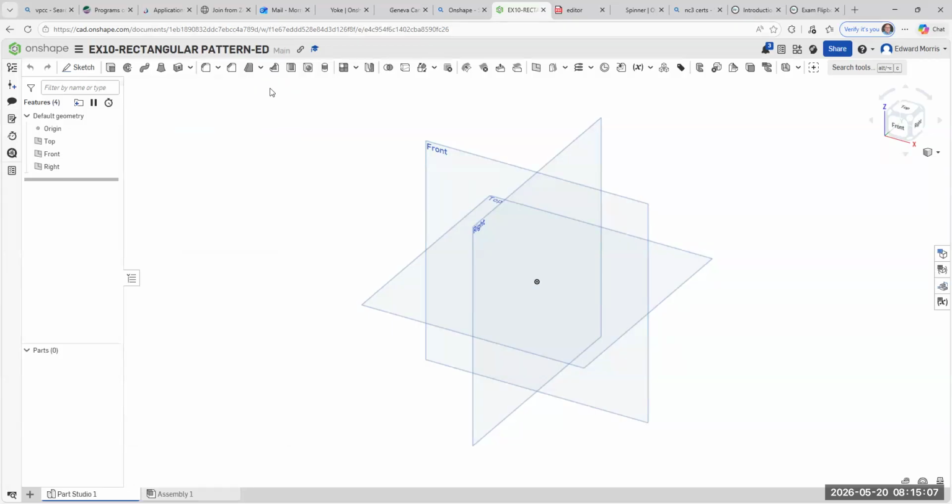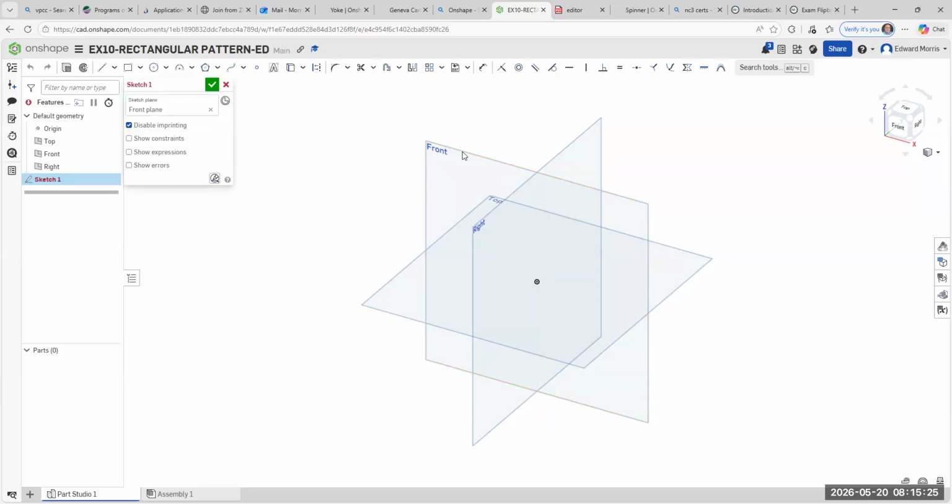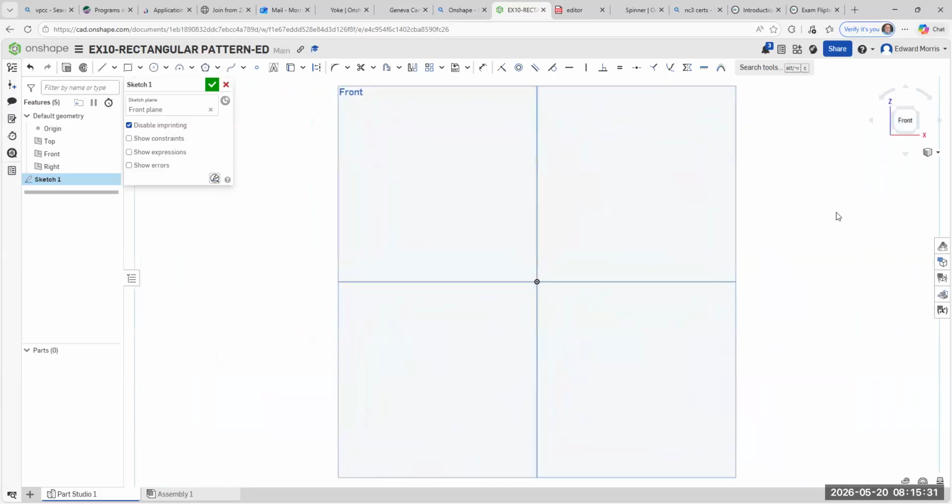All right. Now, I'm hoping you can see your drawing with the lights out. I know y'all like to do CAD work sometimes with the lights out. So that's what we're doing today. Go to Sketch and click on this frontal plane. All right. And we're going to get over to the view cube and select the front.